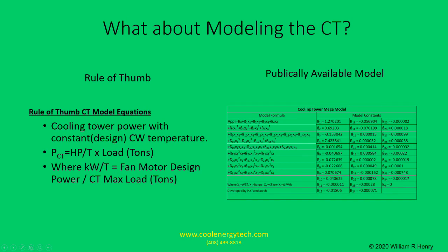For measurement and verification of the cooling tower, we can choose a simple rule of thumb model, such as the one used by YorkCalc, or a more complicated, time-consuming model. The Department of Energy has their cooling tower model, but there is a potentially simpler model that is publicly available. This is the Venkatesh model, shown here on the right. It is a polynomial equation with 35 terms. Still, when I ran this one on my desktop, it took about 24 hours to complete.